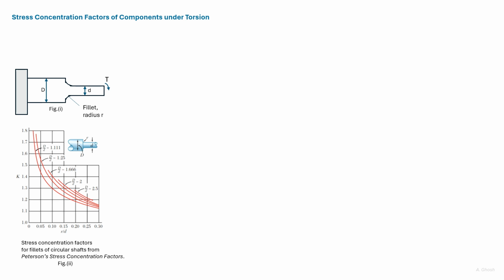Here we discuss stress concentration factors of components under torsion. We have earlier discussed stress concentration factor of components subjected to axial loading. If a component has a discontinuity, then the stresses around the discontinuity are generally higher, and stress concentration factors are used to give these higher stresses.